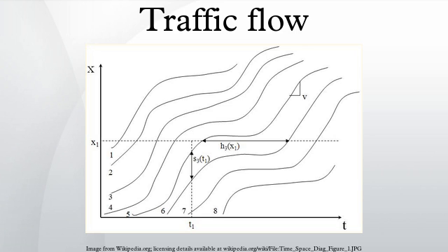There are two main approaches to tackle this problem with the end objectives: system optimum and user equilibrium. System optimum is based on the assumption that routes of all vehicles would be controlled by the system, and that rerouting would be based on maximum utilization of resources and minimum total system cost. Hence, in a system optimum routing algorithm, all routes between a given OD pair have the same marginal cost. In traditional transportation economics, system optimum is determined by the equilibrium of the demand function and the marginal cost function.